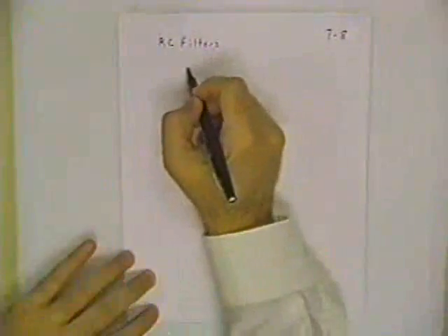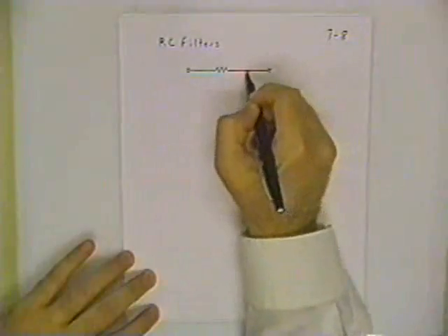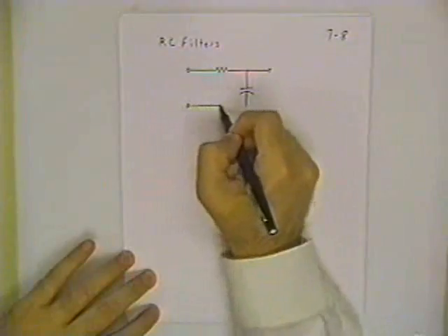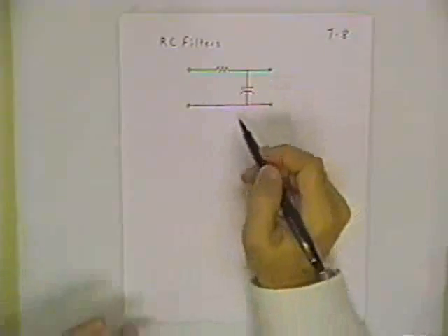All we need to understand these circuits is the basic impedance picture and Ohm's law in its AC form. And in fact, what I'm going to use is the voltage divider that I've introduced earlier with DC circuits, but now I'm going to show you the voltage divider in an AC context, and that'll help us derive the behavior of this filter. This is called a first-order filter because if you went back to solve it as a transient problem, it would have a first-order transient response.